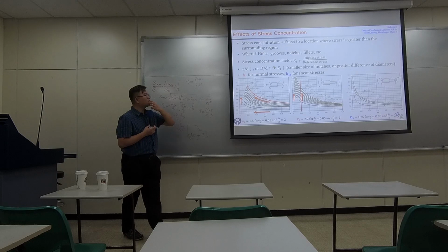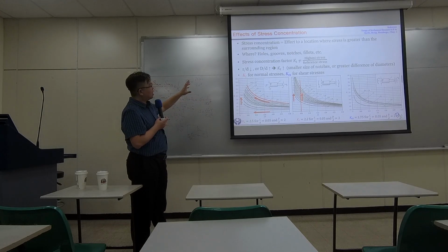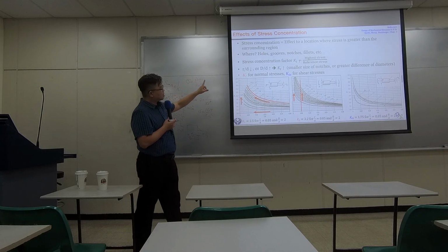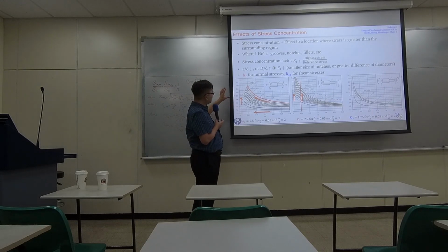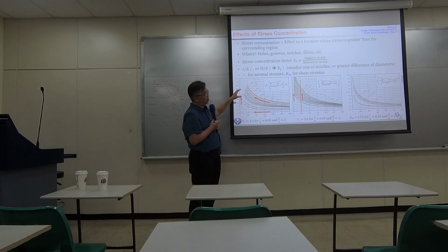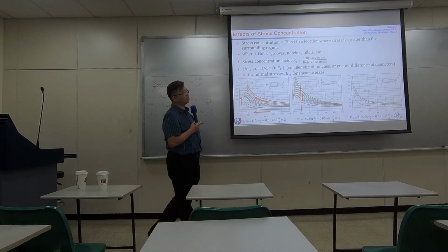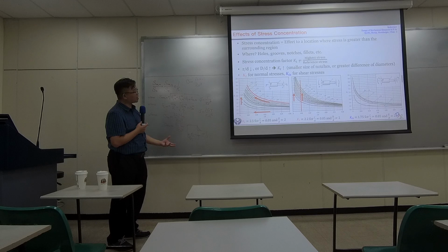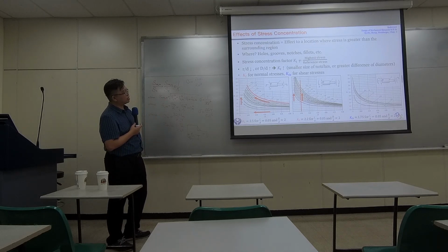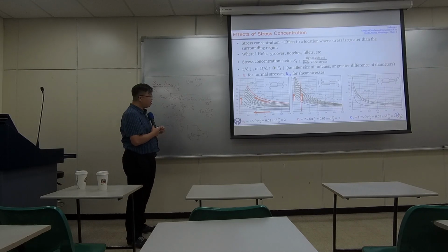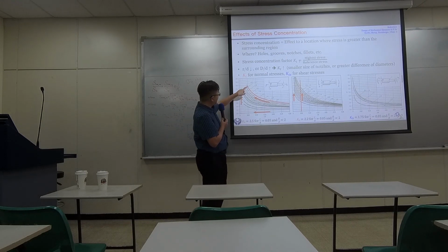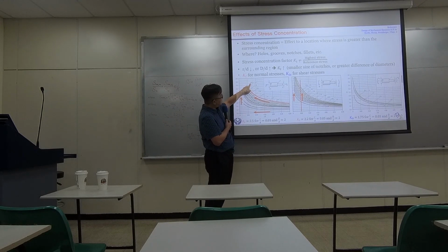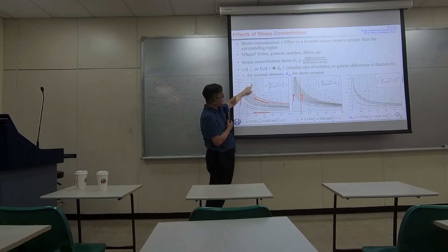Okay? So later on I will let you know, not only this, the stress concentration factor will affect fatigue, but also it will affect static load. Okay? So, which factor will also increase stress concentration? The other factor is this ratio, large capital D over small d.